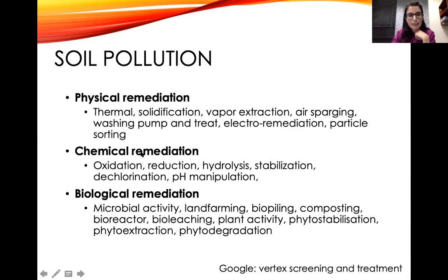Okay, maybe I'll just take one. So for example, air sparging is when you create a vacuum, take pressured air into the soil or into the groundwater, and make the hydrocarbons escape. If oil, petroleum or diesel has leached, or there's been a crack and it has gone into the groundwater or the soil, then you create that vacuum, and sparge it with air and pressure, and take it out from the ground, right?